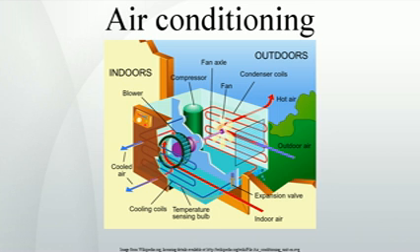Disadvantages are that unless ambient humidity is low, as in a dry climate, cooling is limited and the cooled air is very humid and can feel clammy. Also, they use a lot of water, which is often at a premium in the dry climates where they work best. A typical single-hosed portable air conditioner can cool a room that is 475 square feet, 44.1 m2, or smaller and has at most a cooling power of 15,000 BTU/h, 4.3 kilowatts.